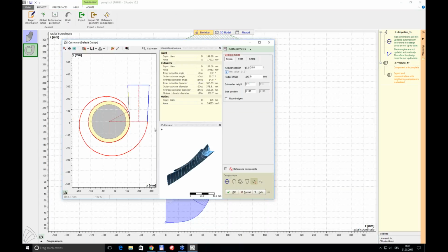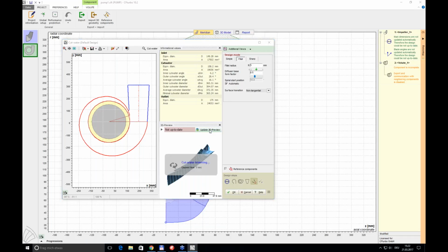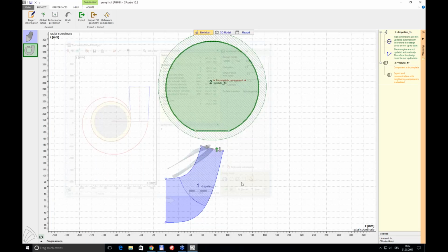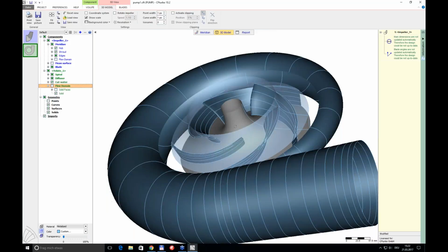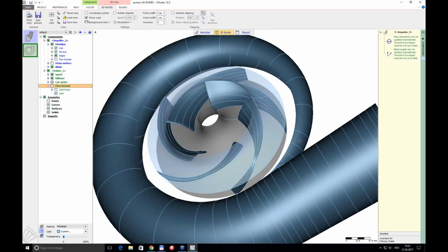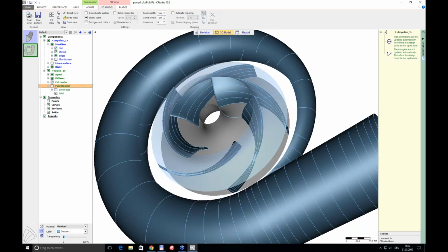the volute. Here I choose one of the three design modes, the fillet mode, and I have to define a certain radius here. I can do a preview again, and once I hit that button, I'm almost done when it comes to the design of the stage.